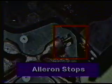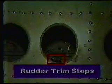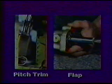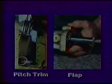Stops are usually referred to by the unit they control. For example, aileron stops, rudder stops, elevator stops, aileron trim stops, rudder trim stops. The mechanical stops for the pitch trim and flap system are internal in their respective actuators.